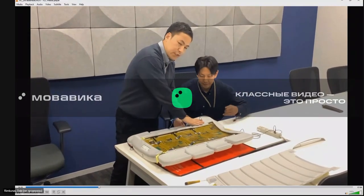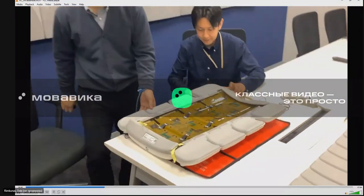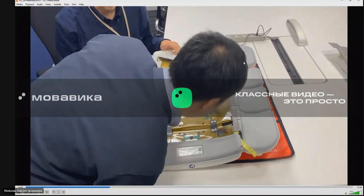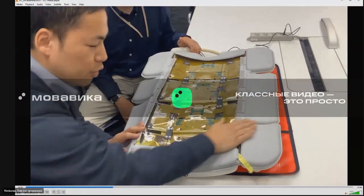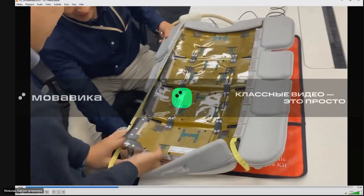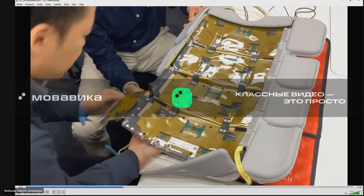Now, the trick with this coil is that these flaps on the side are very easy to tear or break when you're removing them. The guys in Japan have done a really good job about being very careful and consistent about how to remove these without damaging them. This is the hardest part of this coil, is removing it from the housing. You can see it's easier with two people here. And they put this down completely flat vertical and lift straight up. And they're able to lift it up there.